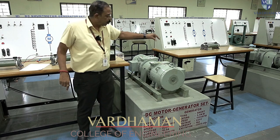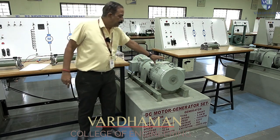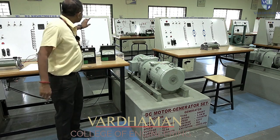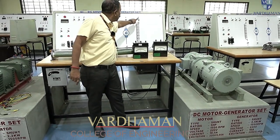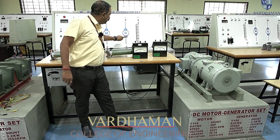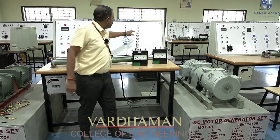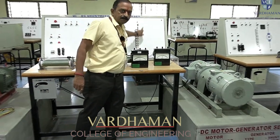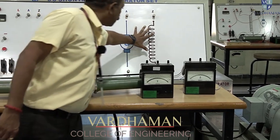That type of electromagnetic field coil we are using in this particular generator. That is represented with ZZZ in the generator section. And the coil which is rotating in between the magnetic field is represented with A and AA. Generally we refer to these as armature terminals. Generally we refer to the others as magnetic field coil terminals. So this is the generator section.